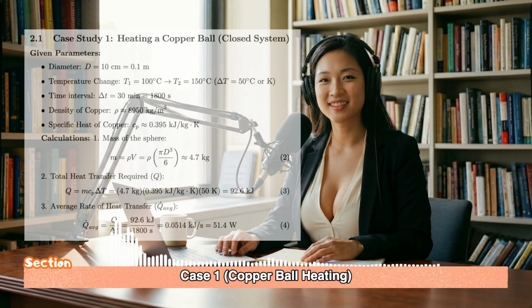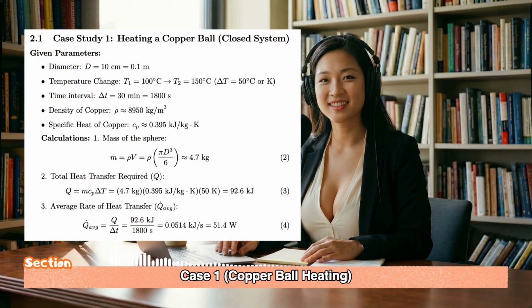Our first case is a closed system, a fixed mass copper ball. We have a 10-centimeter diameter copper ball that we want to heat up from 100 degrees Celsius to 150 degrees Celsius. And the process takes 30 minutes. Right. So before we even worry about the 30 minutes, we need the thermodynamic amount, Q. Okay, so we need the properties of copper. It's got a high density, around 8,950 kilograms per cubic meter, and a relatively low specific heat, about 0.395 kilojoules per kilogram Kelvin. If we run the volume and mass calculations for that 10-centimeter sphere, we find the mass is pretty substantial, a little under 4.7 kilograms.